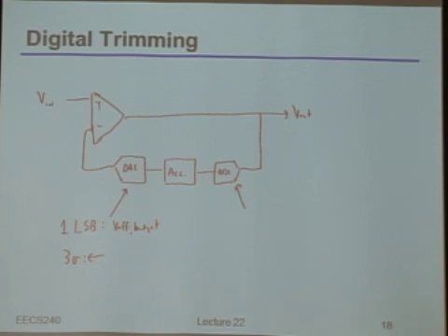So let's go back to the earlier example. Let's say that indeed I had the 7 bits of range I needed in my DAC. Who thinks you also need 7 bits of dynamic range in the ADC? Okay, who thinks you need less than that? Okay, good. How many do you need precisely? 1.5. No, it's actually 1. Okay, we'll see how it is.